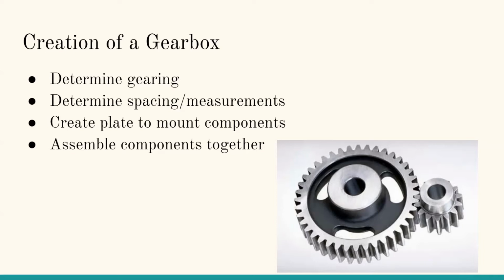Fun stuff like that. But anyway, once you have the gears that you need, in our case, we will be using a 52 tooth gear to drive the axle and 11 tooth pinion gears for the Neos. So once you have the gears you need and a couple other things, like making sure I don't design the motors to be inside of each other, once you have that, you can figure out the measurements you need, and you can start to create a plate to mount the components on, which will be the next portion of the lesson.